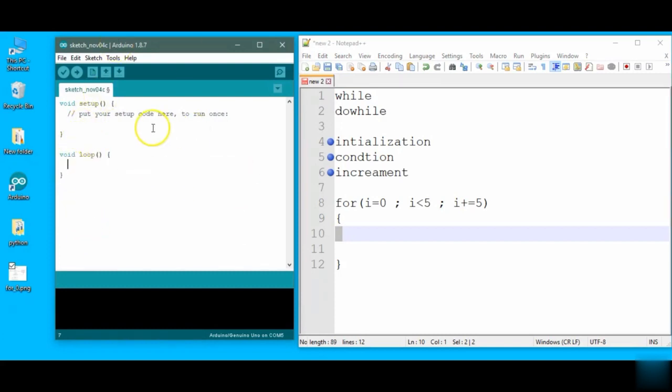So here, first of all, remove this. Now what we are going to do here, we will take an array and give the array certain values or specified pins, and then take LEDs on the pins and just use a single statement to turn on all the LEDs one by one. So let me have int LED pin. Now let me take an array of length 5. Instead of taking 5 variables, we have just declared one. So here the brackets, and 2, 3, 4, 5 and 6 are the pin values.